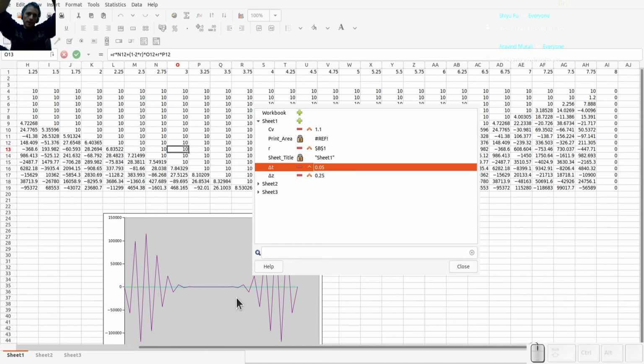You're moving the information further than your delta z, but you're using the immediate neighbors to still average things out. However, in that amount of time, things would have gone way past that. So it's no longer valid to use the neighbors, because the wave of information would have gone beyond.